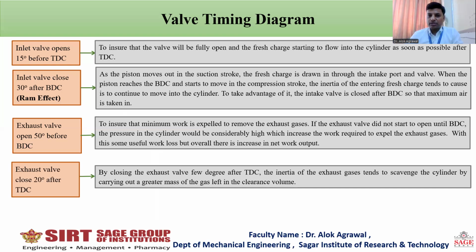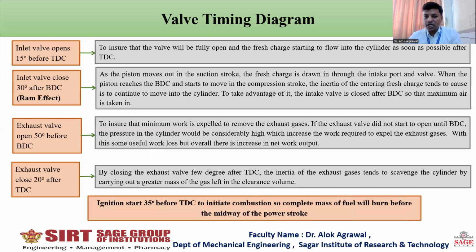Now the ignition starts 35 degrees before TDC. It is to initiate the combustion process before the power stroke starts, so that the maximum fuel will be burned and the power stroke will be more effective. So these are the reasons why the valves do not open and close at dead center.